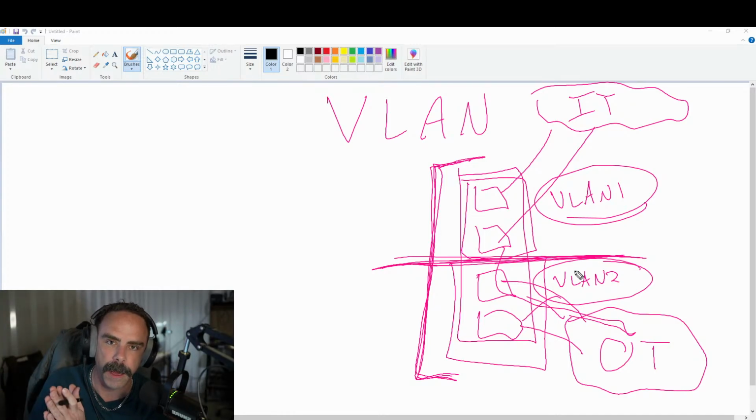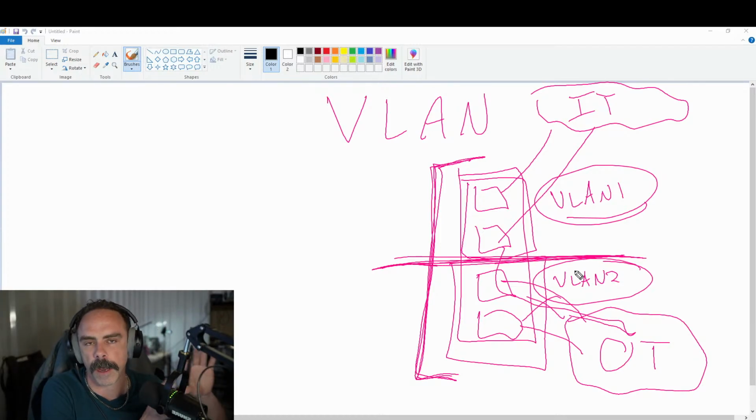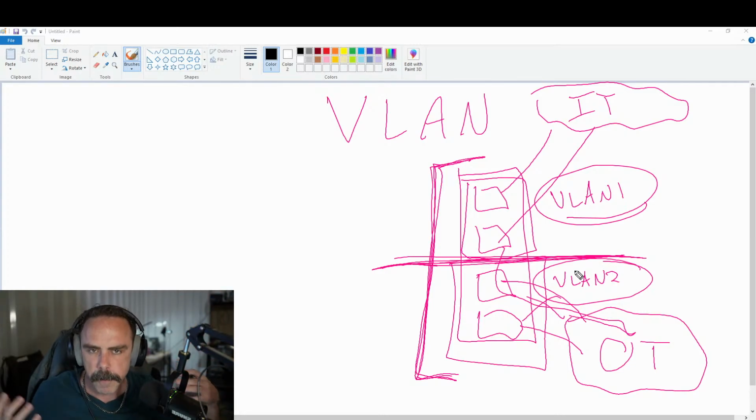But we're going to VLAN you so that your broadcast messaging, your UDP messages that really corrupt and clog up traffic, guess what? You're not going to mess with our Siemens OT Profinet network. Even though we're on the same physical layer, you're not going to mess with us. So that's what we do. We VLAN off, especially Rockwell drives. And so that's how we do it.